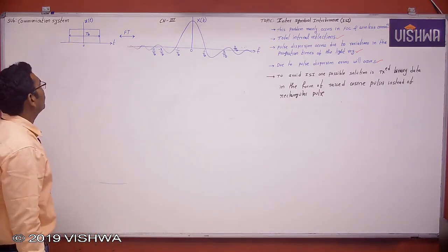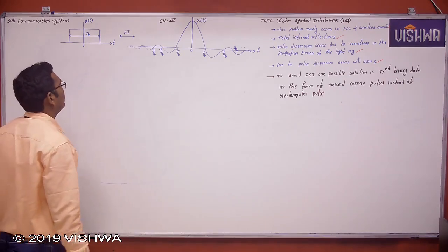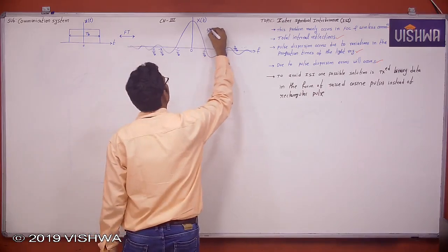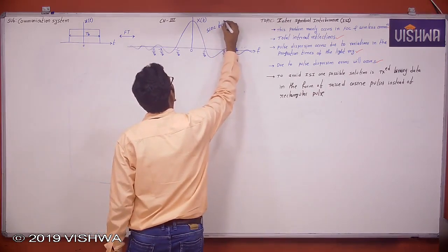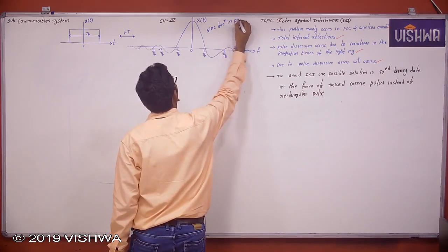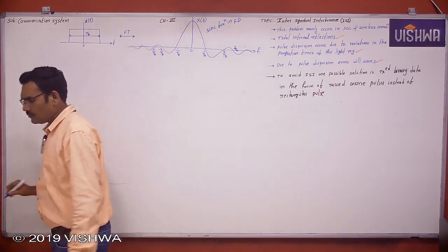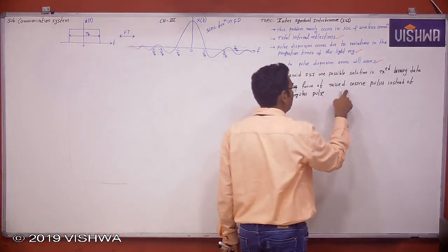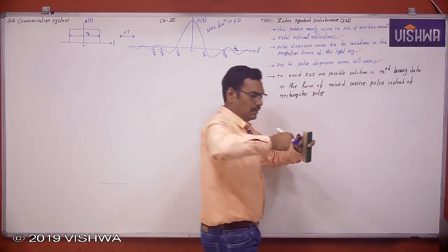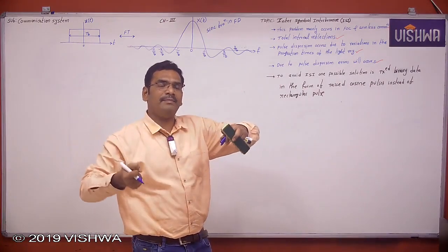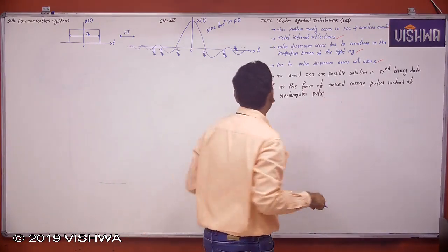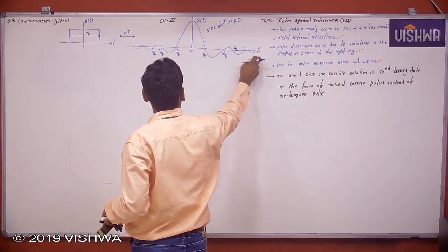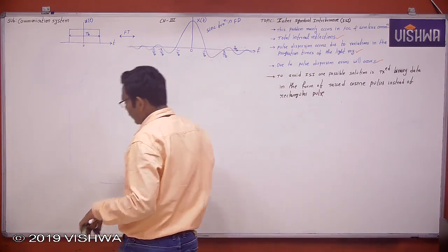The Fourier transform of the rectangular pulse is a sinc function, right? Now this is the sinc function in which domain? Frequency domain. Now you tell me, what is the meaning of raised cosine pulses? A raised cosine pulse should be a spread pulse in time domain. I want it in time domain, but this is in which domain? Frequency.